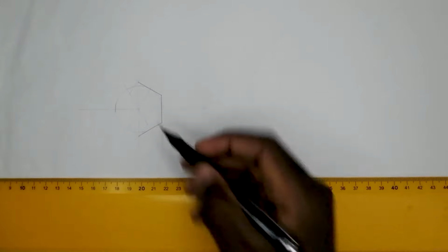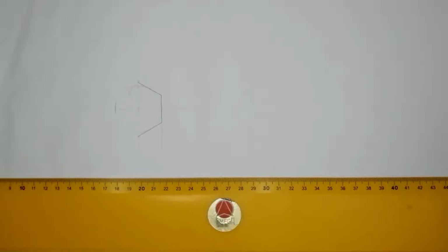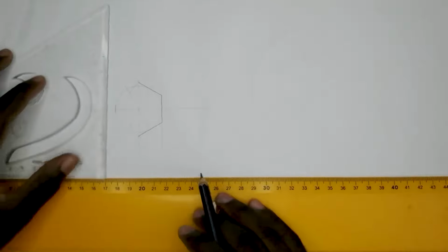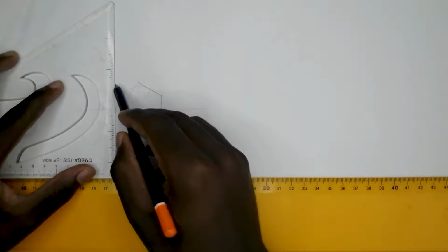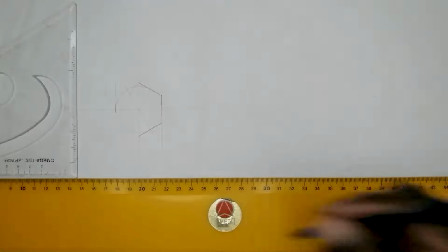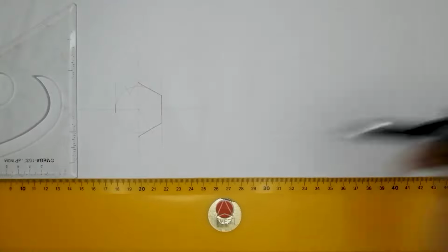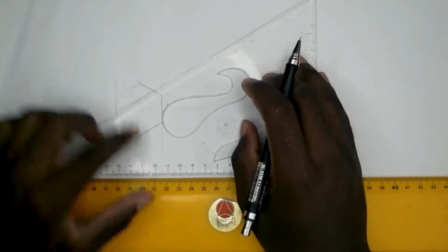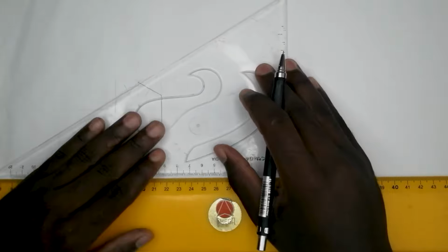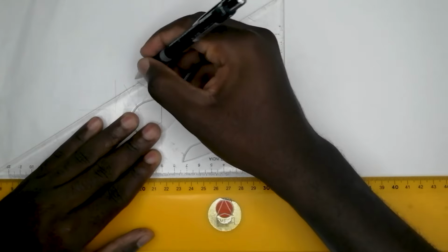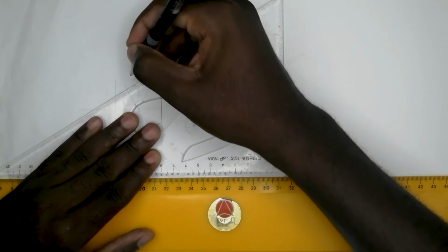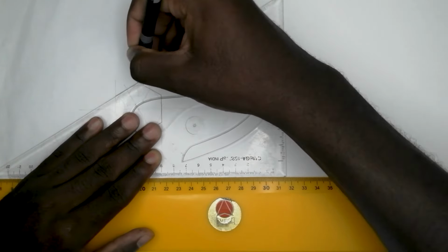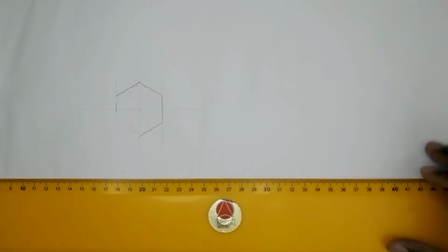The only side that remains is the one on the left top there. Before we draw it, we will need just a small construction line here to show us where our side is supposed to end. After we have that construction line, we'll go to this point of tangency with our set square using the 30 side, and then draw a line. So that shouldn't be very difficult.